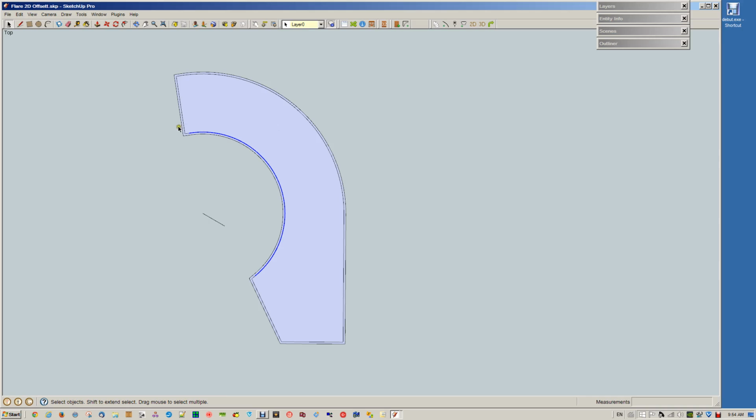stringer run. Now what makes life easy here is that little spot right there and this little spot right here. We can delete those and then triple click on this part and clean it up. It's that fast. The outside one, we're going to go with an extra 17 millimeters because we want to have the treads rabbited into the stringer by 10 millimeters. So 10 plus 17 is 27, which is exactly half a 54 wide stringer. So let's do it.